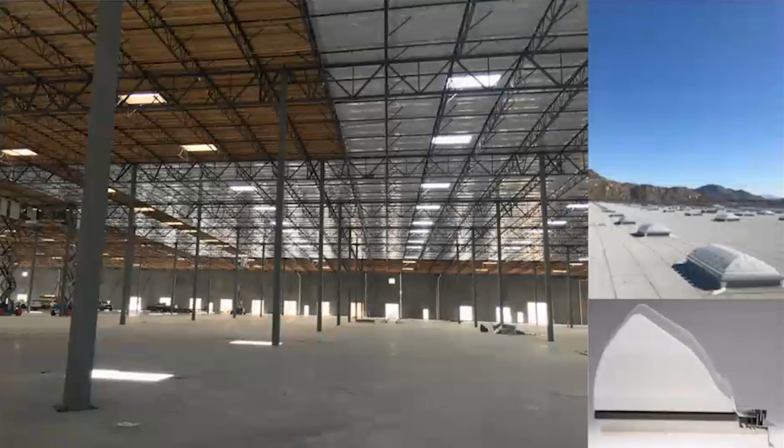And then we have another system I haven't introduced yet, and that's the use of prismatic lenses. So this is a dome-style skylight, and there's a few manufacturers of products like this, and the inner dome is prismatic. So what it's producing is a very diffuse light, or 100% haze factor.